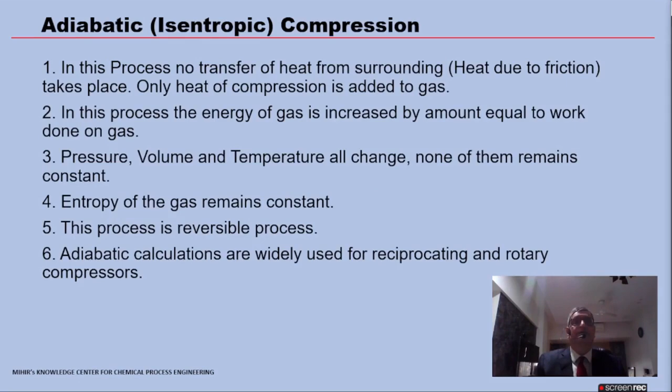Now, adiabatic isentropic compression. In this process, there is no transfer of heat from the surroundings, that is, no heat transfer takes place except heat due to friction. Only the heat of compression is added to the gas. In this process, the energy of the gas is increased by an amount equal to the work done on the gas.